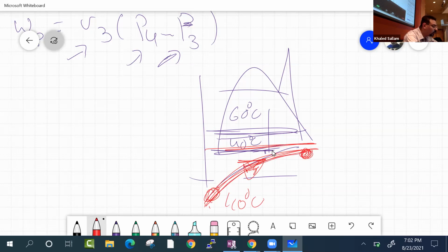and the cooling water coming from the cooling tower goes to your condenser, it gets heated. It gets heated to what? Above 40. I mean, it's coming at 40 to us. Then it will go up to, I don't know, depending on how much water is going, but it will increase to 45, 50. So this is not going to work. You will probably have to set hotter than that because it's cooling you. So what is really determining the condenser is the temperature of the air outside. So on a hot day, that temperature will go up and push the condenser temperature and pressure up. And on a cold day, that temperature goes down and takes your condenser temperature and pressure down.